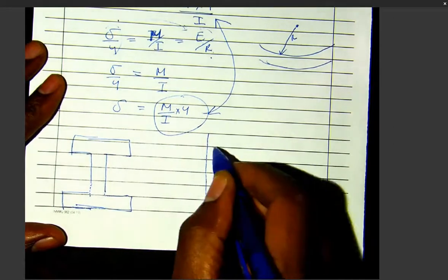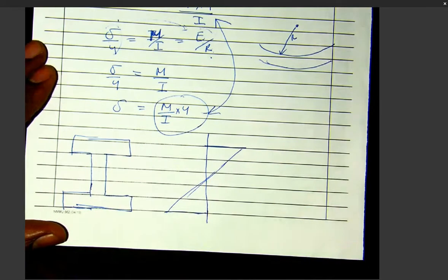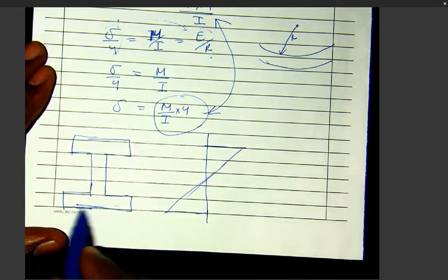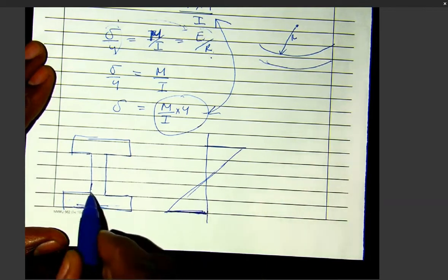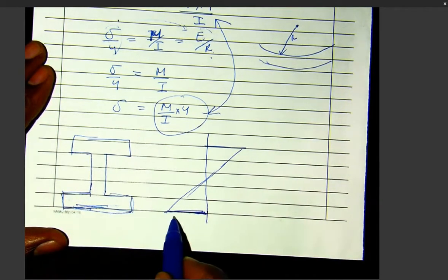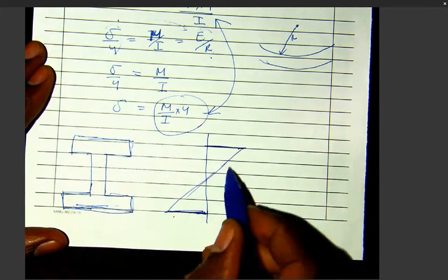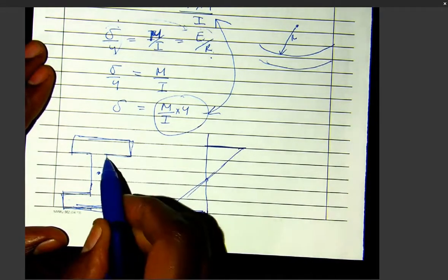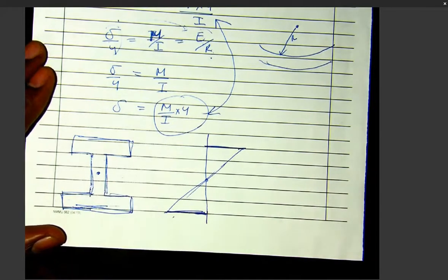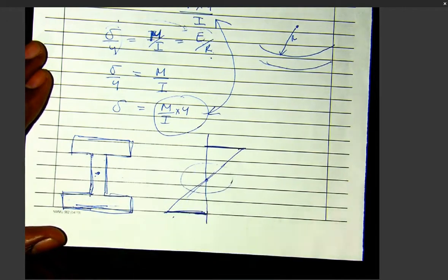You can even see the profile of the section. The bending stress is going to be something like this. You can see the area must handle those stresses at the bottom of your beam. You've got a wider, bigger area there for those stresses. As you go towards the center of the section, the stresses tend to be 0. That's why you don't need a big area around there, because the stresses are getting smaller and smaller and smaller.